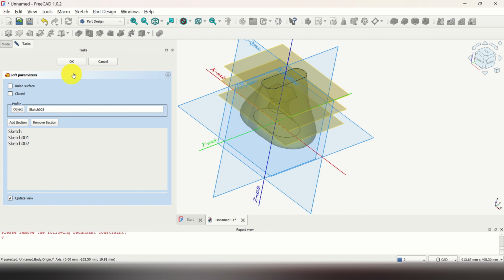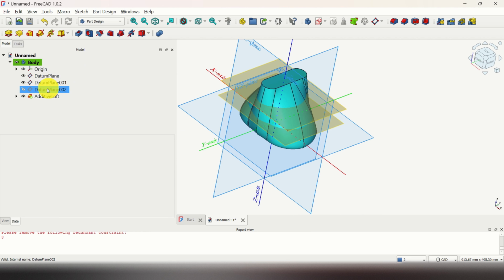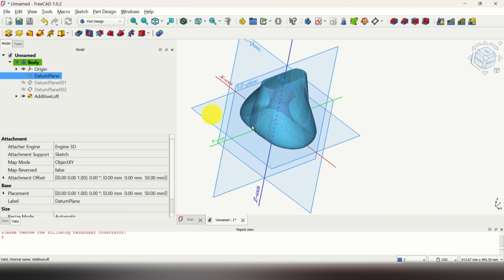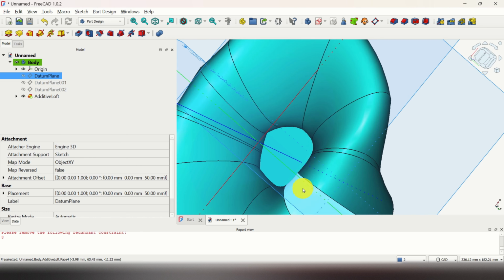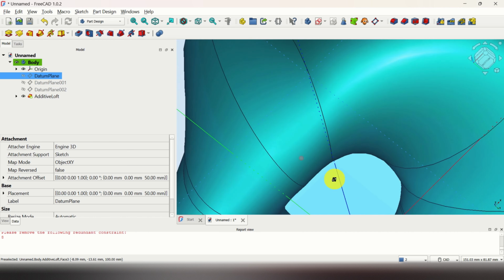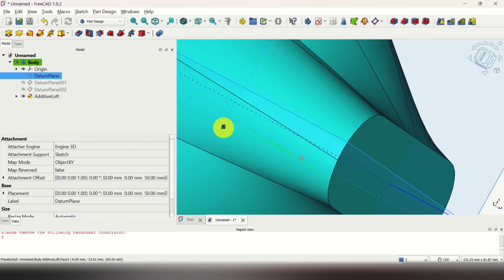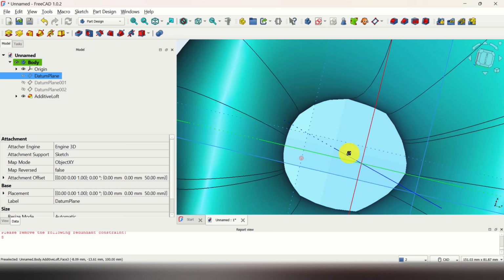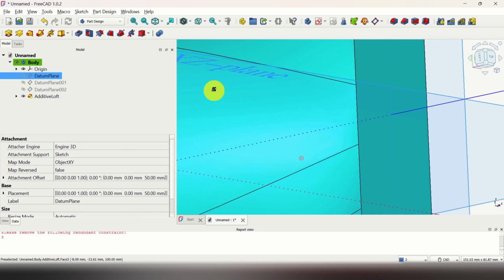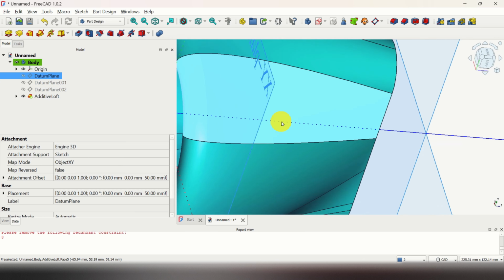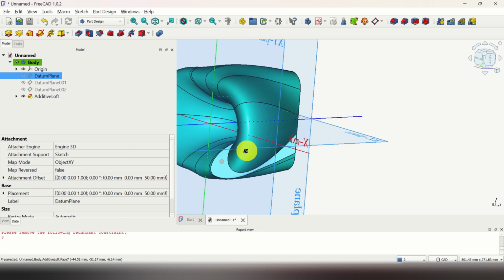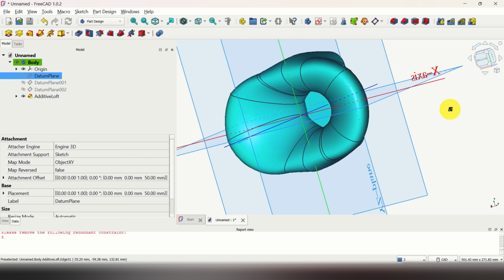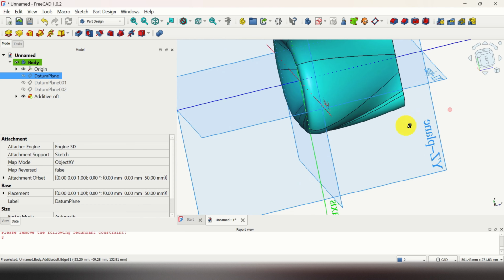We get completely different shape. If you click on OK and if you click what happened and if you deselect these planes, you will see what you got. You got something that looks really, really complex. Since over here, you also have some inside shape. That is, this looks more or less like a closed surface or something similar, or it has some internal shape. That's why it's very important to properly and in a particular order select the sketches when constructing lofts.